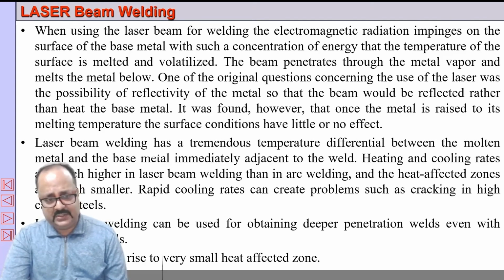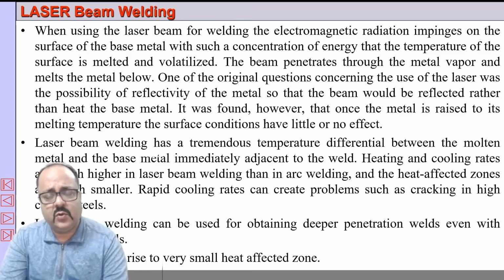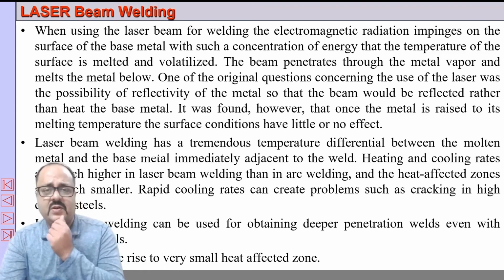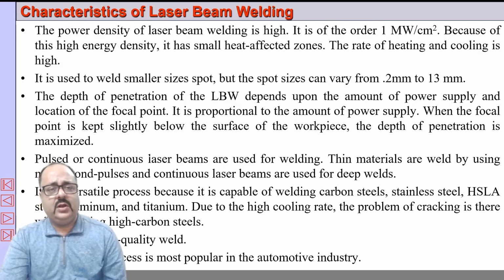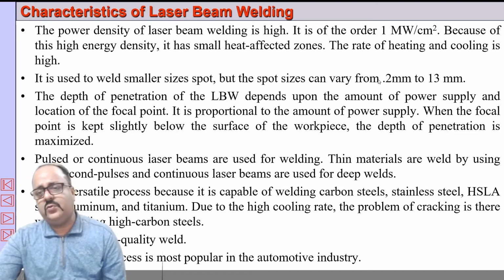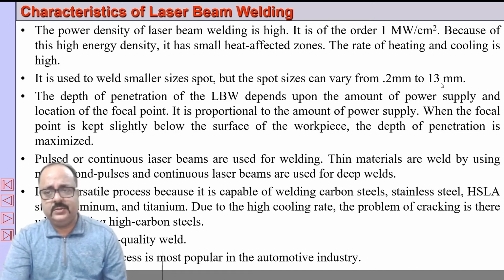So deeper penetration is obtained. Heat affected zone is very less. Again, there can be conduction mode or keyhole mode of welding depending on the beam width. And the spot sizes can be from 0.2 mm to around 13 mm. It can be pulsed or continuous.